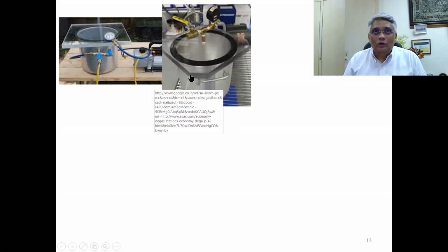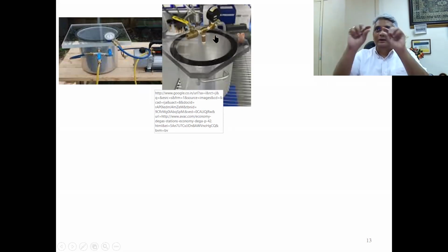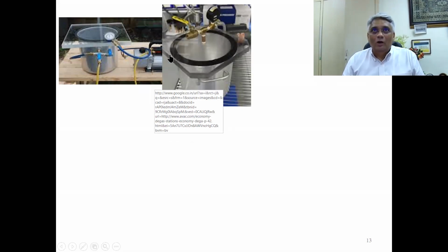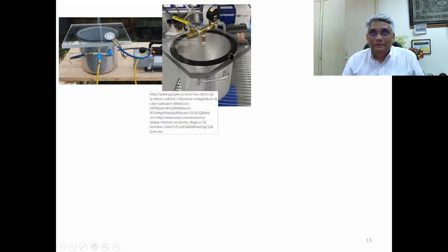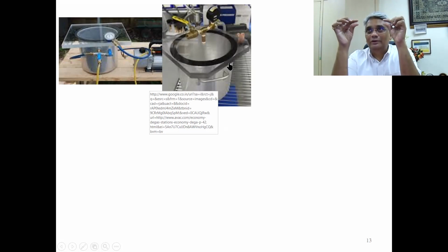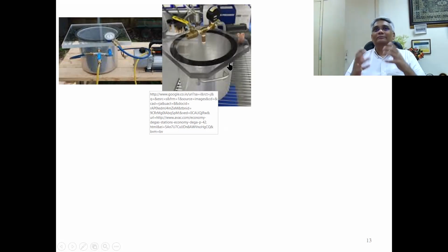So see the top plate there, this is required because that's where the suction happens. And what is required is a good seal. That seal is called the O-ring. It's made of neoprene, a plastic bead that sits there on top of this bottom vessel. And that is so when vacuum suction happens, this rubber contracts a little bit, and that makes it airtight. That's it.